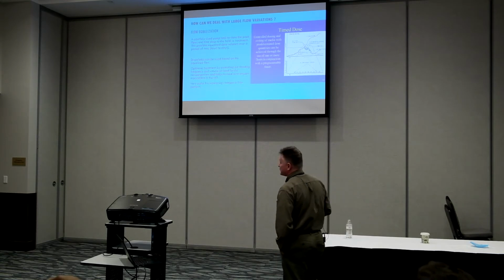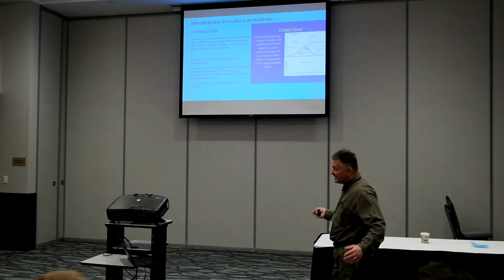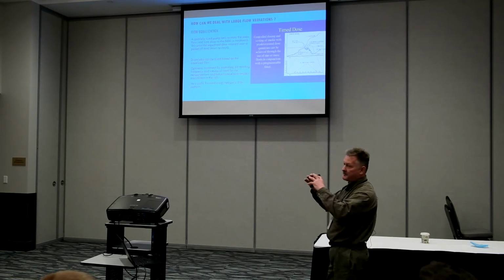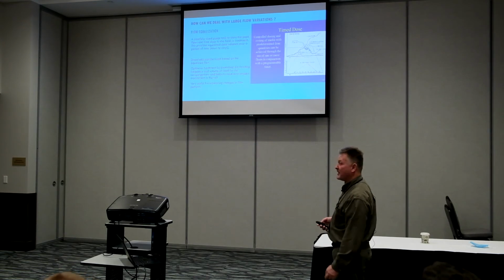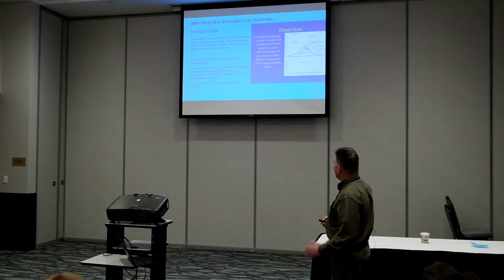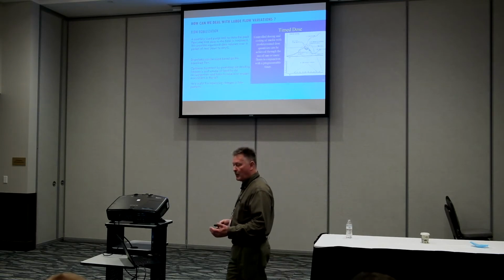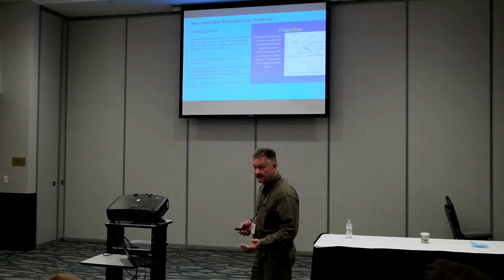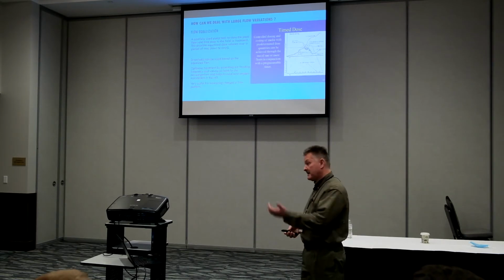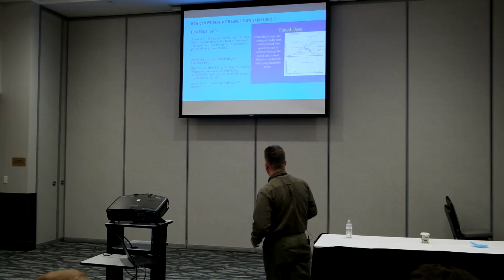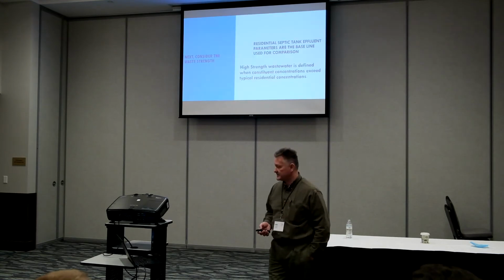It optimizes treatment, as I mentioned, because we're literally just spoon feeding the bacteria instead of giving them a huge slug of food and all of a sudden they just populate, and so we're kind of creating a little starvation effect and keep them hungry at all times. Secondly, it's very useful for monitoring any kind of flow changes. For instance, a leaking toilet can put out an extra 1,000 to 2,000 gallons a day. Flow modulation or flow equalization can help track potential issues of systems.